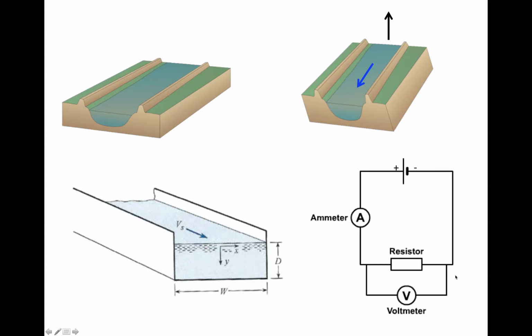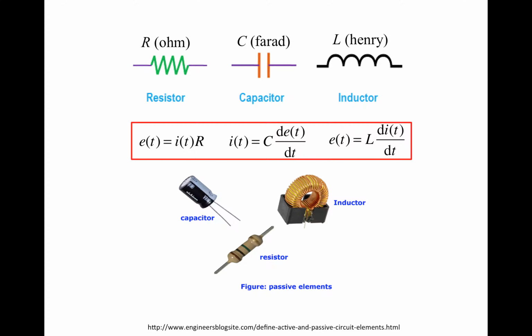The voltmeter usually has a resistance that's much larger than any normal resistor. So it's going to appear as a wall that almost completely blocks the flow of current. As a result, most of the current will still flow through this normal resistor, because this is a wall that's blocking the flow. So the voltmeter is not going to disturb the entire circuit in any significant way. So that's current and voltage.